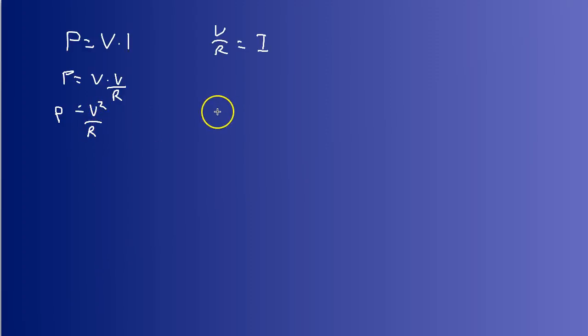So power can also be calculated by multiplying V squared divided by resistance. If you have a short circuit in a battery, you have some voltage and very little resistance. So resistance is really close to zero. It's not zero because everything has some resistance, but it's really close to zero. So if this value is really, really small, and this value is getting squared, so it's kind of getting amplified, then we produce a lot of power. And that power turns into heat.